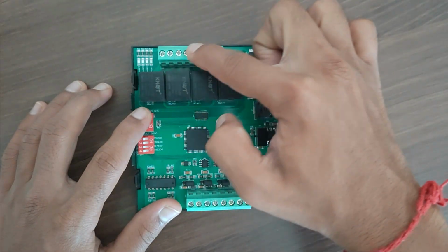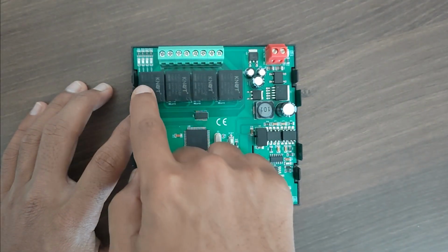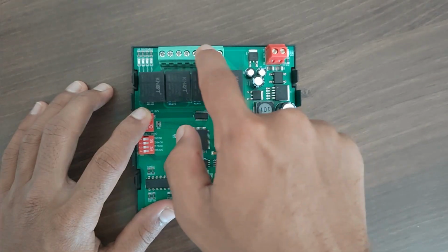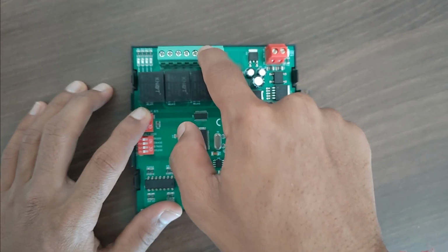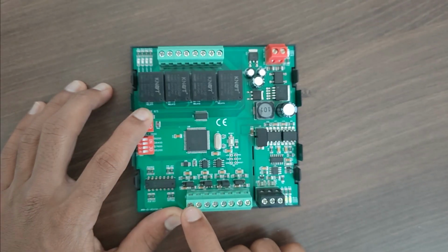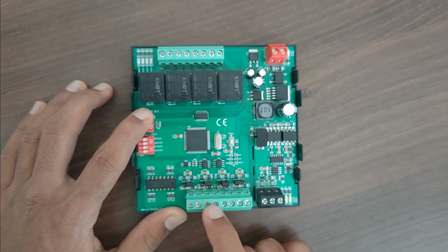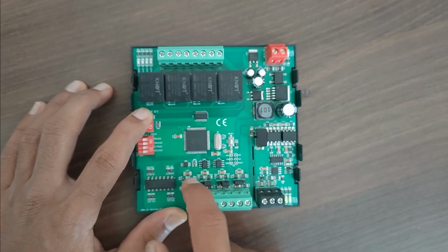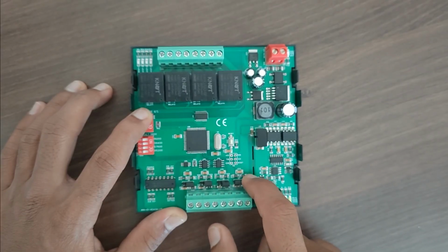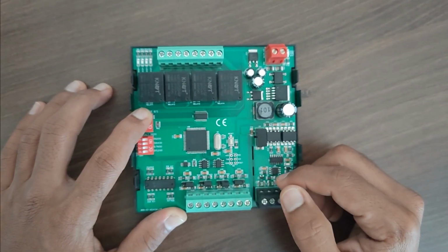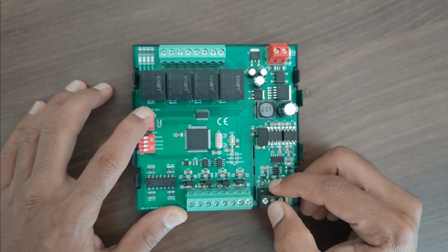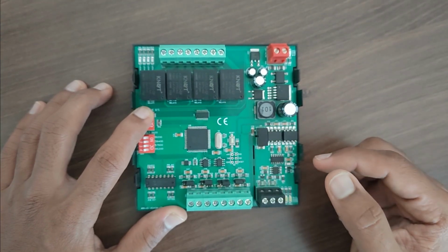And here we have the DO part, that is operated through relays, where you can connect relays, switches, motors. And here we have the EO part. For this EO we have the jumper provision, that is for 10-bit and 12-bit provision. So just by shifting the jumpers, we can set the analog output provision as 10-bit or 12-bit.